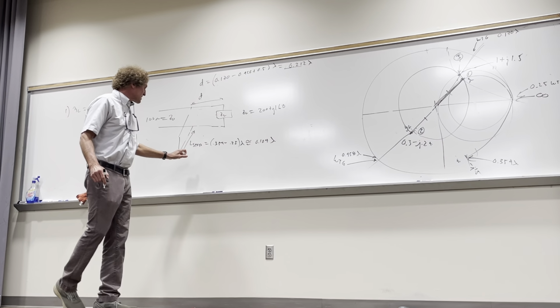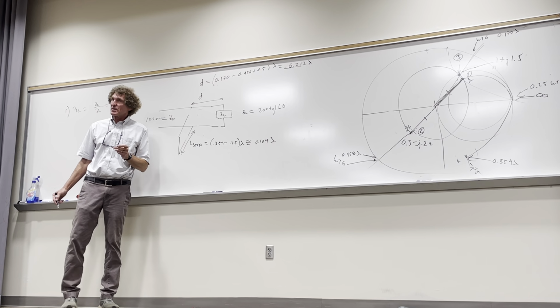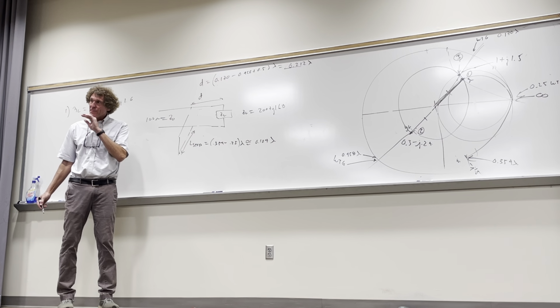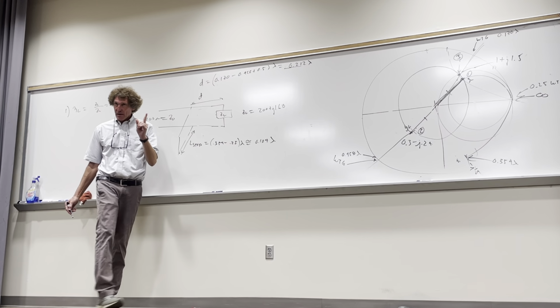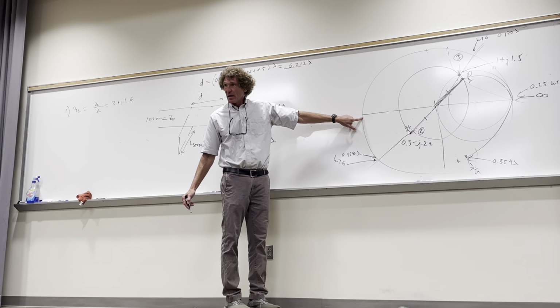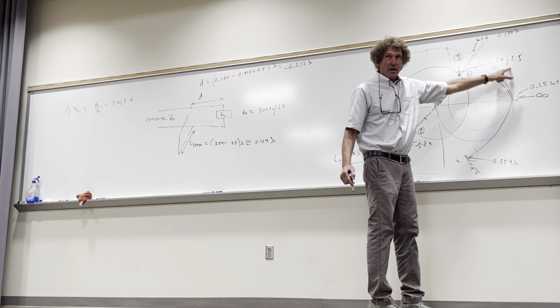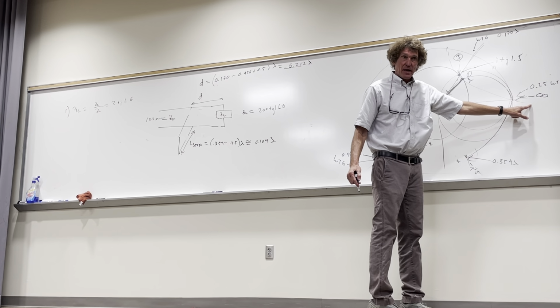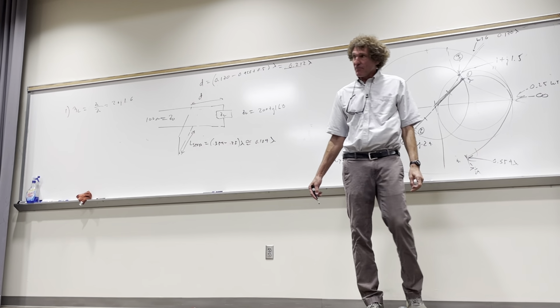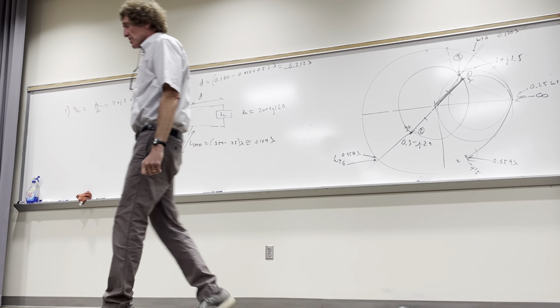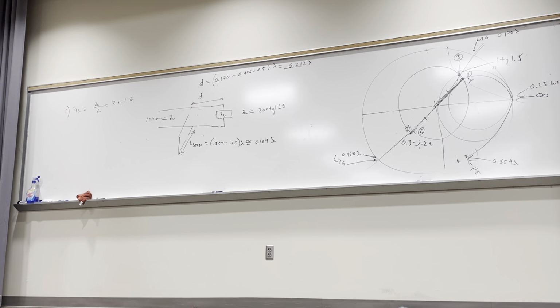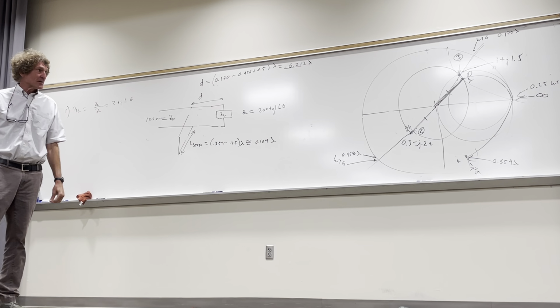What if it was an open stub? If we wanted to match it and it wasn't a short, but it was an open stub, what's the one thing that changes? Where you enter. Now I start here, and I have to go a full quarter wavelength, and then add all this to it. Do y'all follow me? So that would be the difference if it was an open circuit stub. I'm not going to give you an open circuit stub. If I give you a stub, it'll be a short. I can't be more clear. But even then, I'll see somebody come up with a way to make that open circuit stub work.